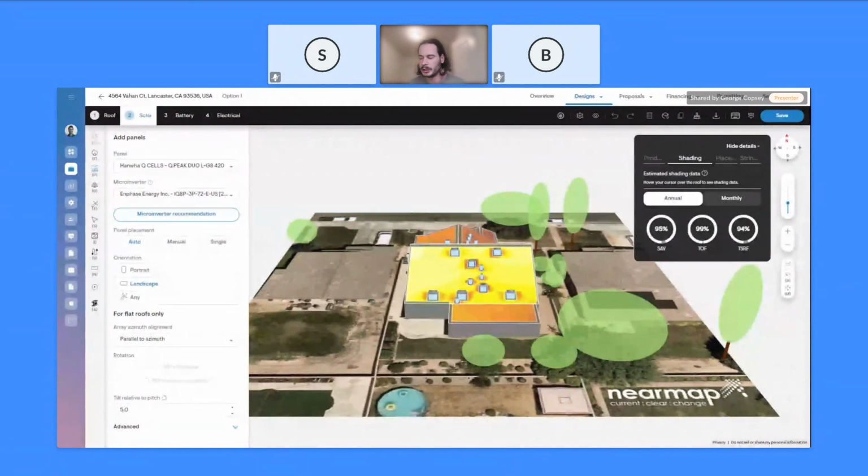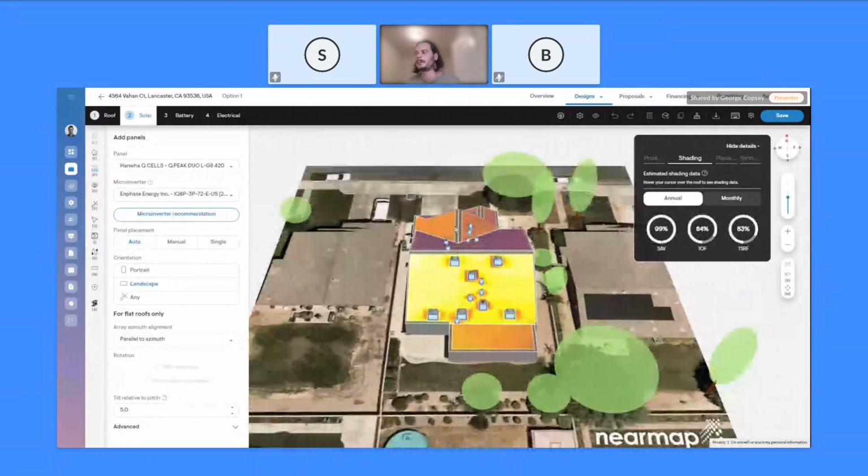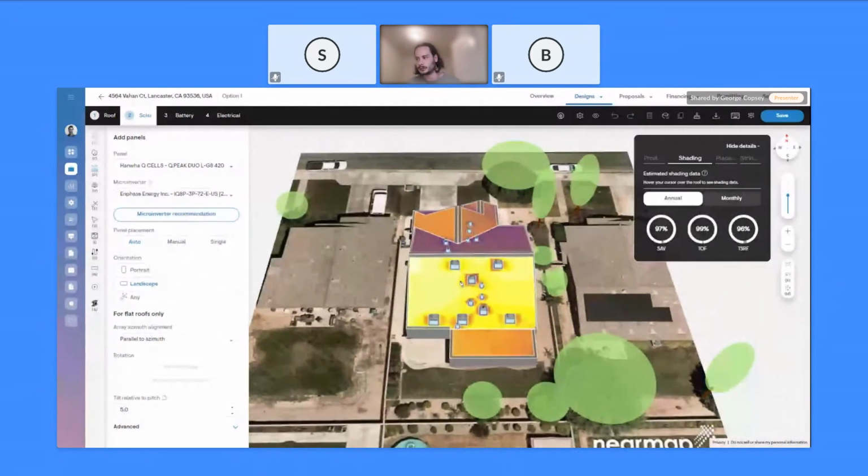with optimal conditions. So these two, SAV and TOF, will be multiplied together to give us what we call total solar resource fraction, or TSRF. And that is really the number that gives us the best indication of where on this roof we should put our modules to be as efficient as possible. And that value is calculated, well, all these values are calculated for every pixel on the roof for every hour of the year. So it's a really large calculation that just happened there.